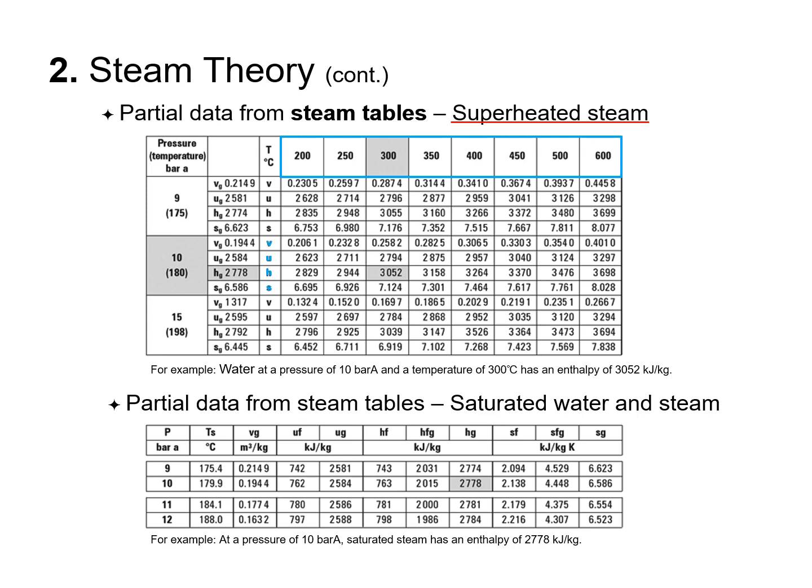For example, water at a pressure of 10 bar absolute and a temperature of 300 degrees Celsius has an enthalpy of 3052 kilojoules per kilogram. The table below gives information about saturated water and steam. It shows that when the pressure in the water is higher, it requires more energy to make it stop boiling, which results in a higher boiling point.